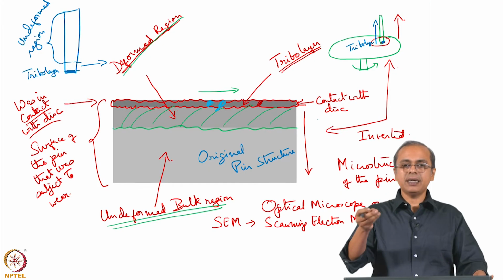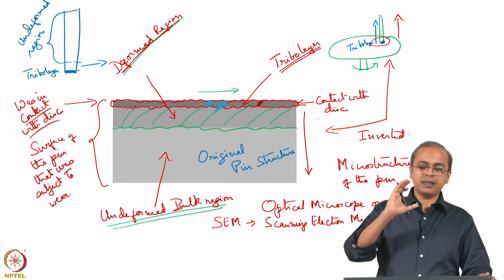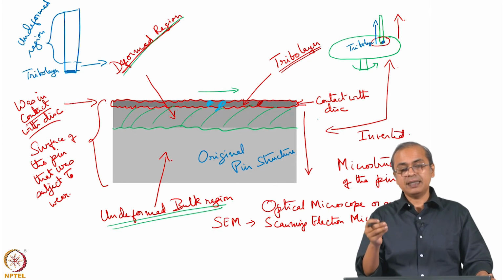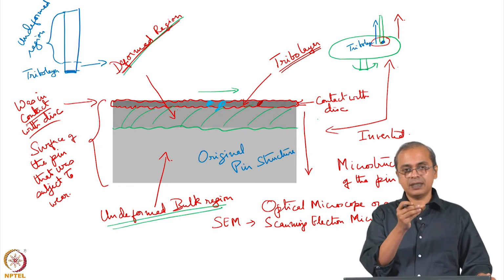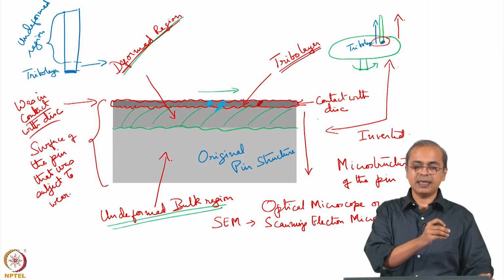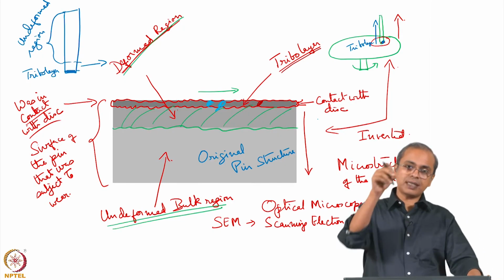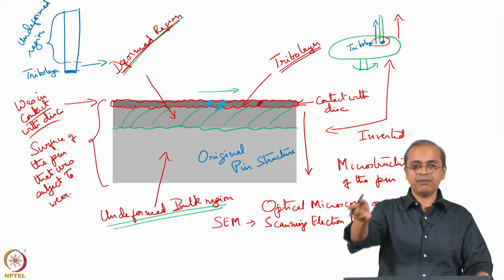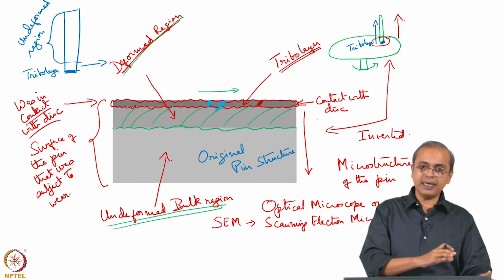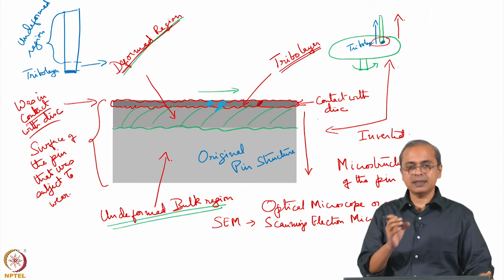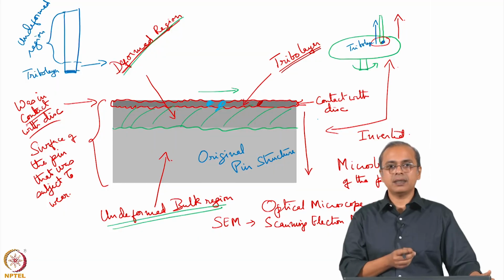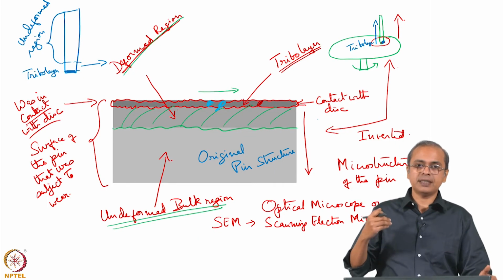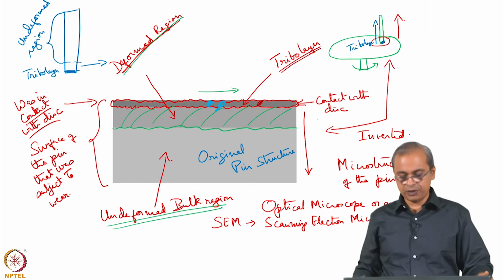It is like thinking of muddy water, as I said, flowing through a pipe, and let us say it breaks off some particles of the oxide layer of that stainless steel. Then those particles further impact the pipe further down the line, and so both the mud particles in the water as well as the debris that has come from an earlier location in the pipe act on the later location of the pipe.